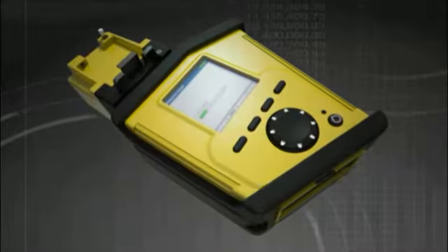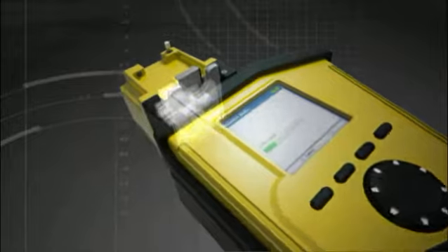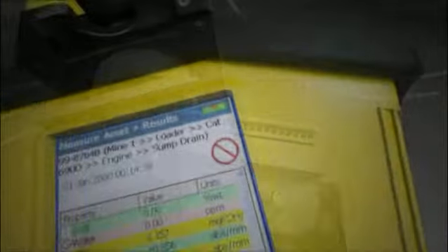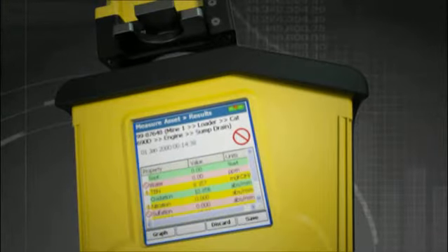When the operator initiates the analysis, flashing infrared light beams are focused on the fluid. Light at some infrared frequencies will pass through the fluid, while at other frequencies, the light will be partially or totally absorbed. The light that passes through the sample goes to the spectrometer. In the spectrometer, the light enters a solid-state waveguide that channels it to a diffraction grating. The grating disperses the light much like entering and exiting a prism, and creates a spectrum similar to a rainbow. The dispersing light from the grating is then channeled via the waveguide to a detector array that records the intensity and frequency of the spectrum.